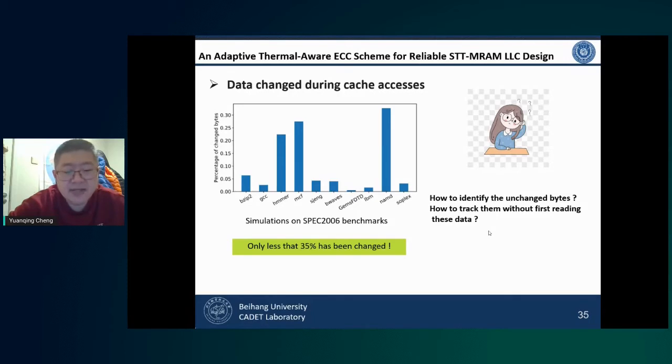They only write back the changed bits. But this read operation aggravates the write latency, because the write latency is already long. Before you write, you have to read the data back again, and the write latency now becomes the original write latency plus the read latency.